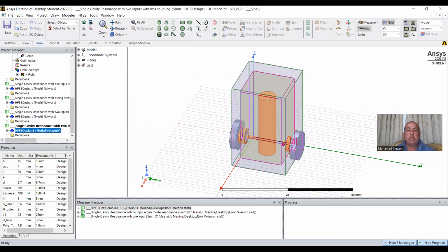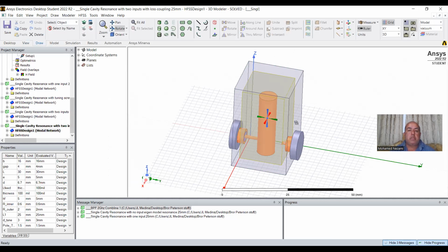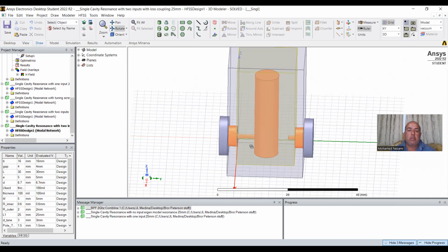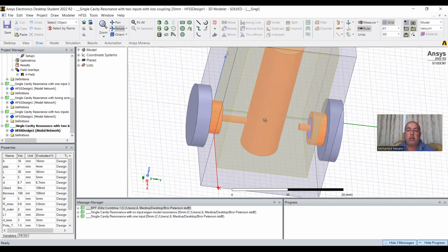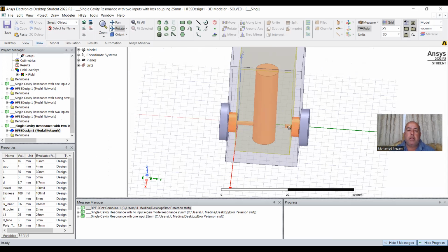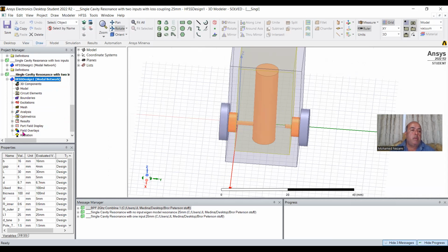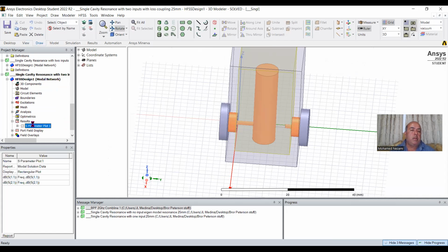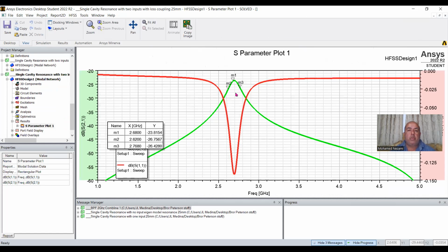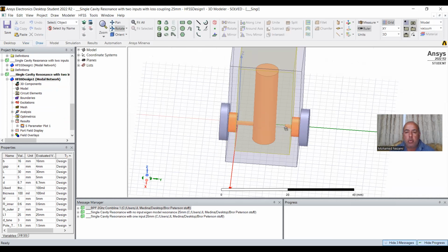So that's basically this here. As you can see, the resonator in here was connected to the input. But the output we put lightly coupled, because we don't want to load it. And if you look at this, usually what you want to do is compute the 3 dB bandwidth, and you need to be at least 20 dB down, because how much coupling do you want to get? You want to get close enough to get a signal, but you don't want to load it.